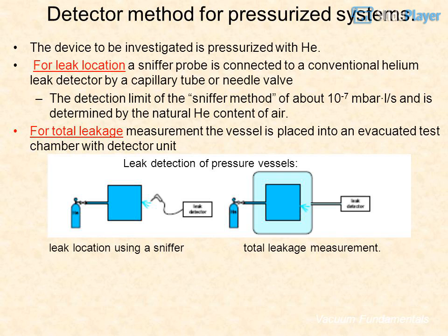For total leakage measurement, the vessel is placed into an evacuated test chamber with a detector unit. Leak detection of pressure vessels. Leak location using a sniffer. Total leakage measurement.